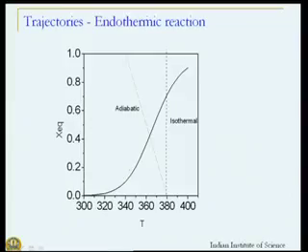So, the reaction rate will go to a high value almost instantaneously, whereas in a plug flow reactor, the increase in temperature will be gradual. So, increase in rate also will be gradual. So, as a result, in a stirred tank reactor, the residence time will be much shorter than the plug flow reactor.